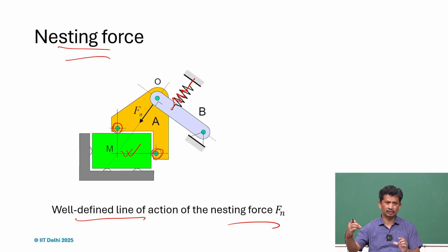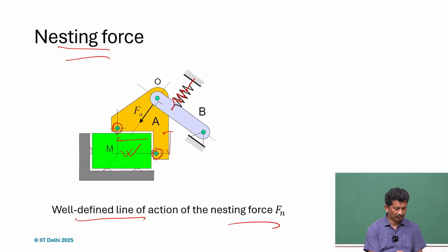It can be just hidden on one side. These distances will also add to the problem, because ultimately there is friction involved here, and that will also lead to positioning errors. So we try to restrict within a certain zone, and we can even think of using flexures for loading.